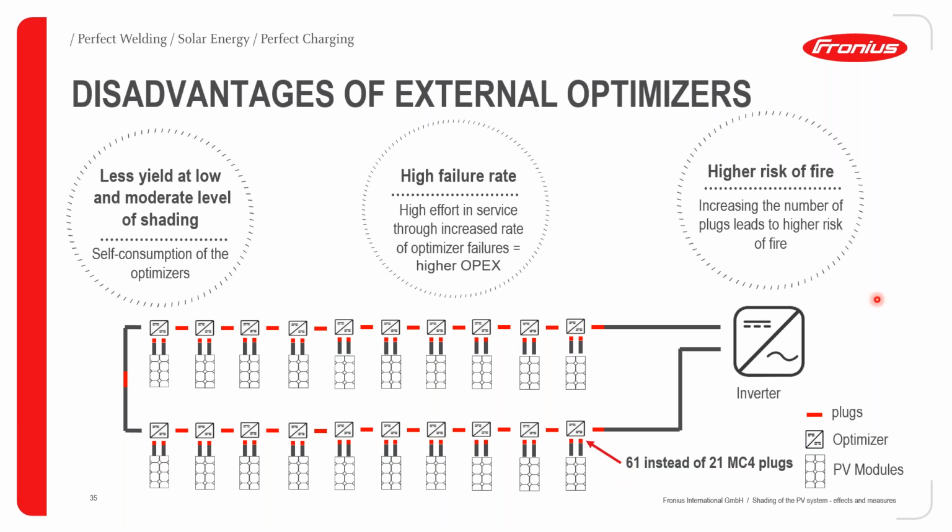There is a possibility that you're going to have a mismatch of the plugs, or some of the plugs are not going to be properly clicked together. This will bring about some loose connections, and with the loose connections or mismatch, you're creating hotspots. If there's a bit of sparking, that is already a higher risk of fire than in conventional installations.